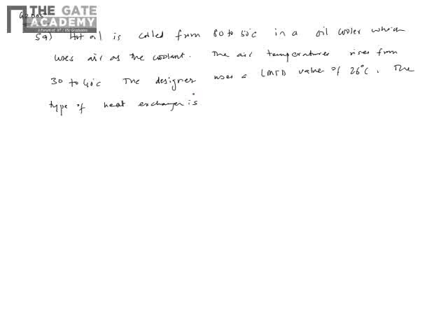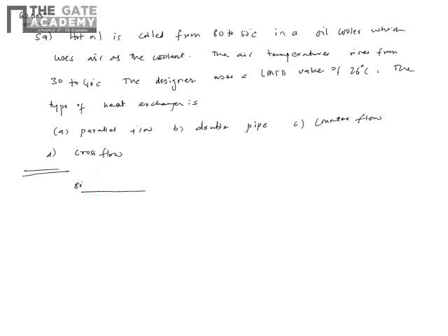Okay, so he uses a value of LMTD, and let's see what this problem helps us to learn. So these are the options, guys. First thing is oil, the hot fluid. It enters at 80, leaves at 50. Let's first take, because one thing you have to understand in this LMTD calculation is that the LMTD for parallel flow is the lowest and counter flow is the max.